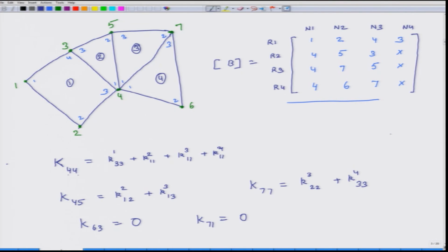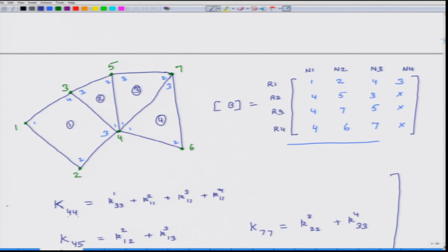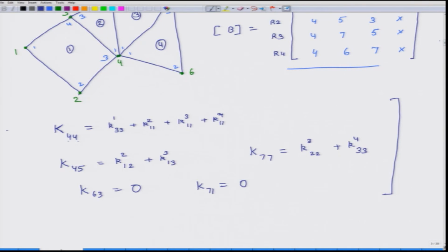Okay. So, using this thought process, by looking at the picture and how things are connected, you can develop expressions for the K matrix as well as F and Q vectors, and if you have to develop equations by hand using this approach, you can write down the equations very quickly. But it is important that you clearly label global nodes and local nodes very clearly and do not get confused between those two, otherwise you may end up writing incorrect expressions.